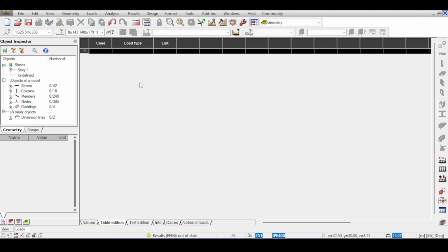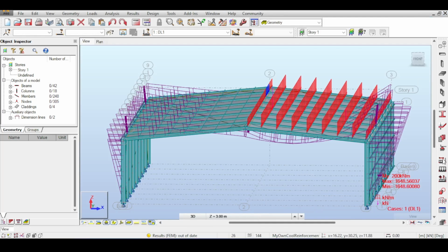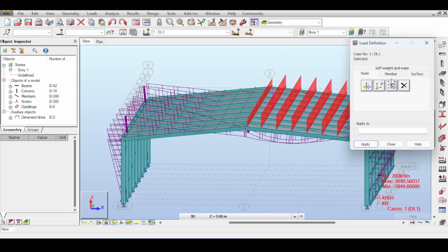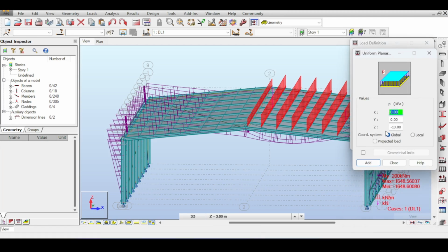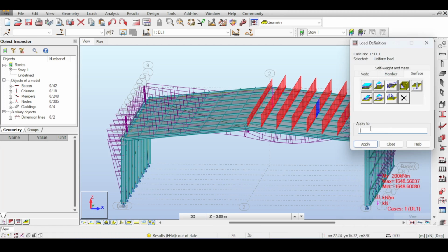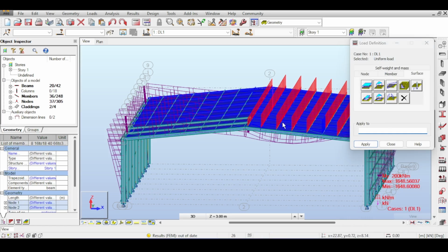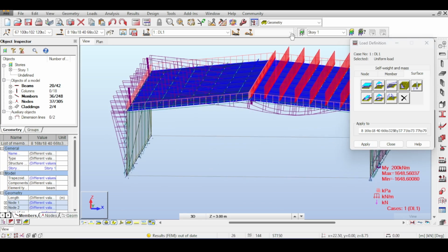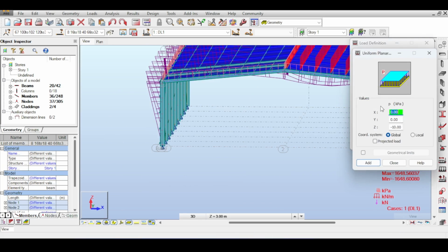And now I'm making a dummy load. So I'll make me a dummy surface load of -10 for the cladding. So I'll select those two things. Of course, I selected claddings and nodes and whatever, but it will only apply the forces on the cladding. So that's perfect. And now I will add me a force in the x-axis being 1 kilonewton.